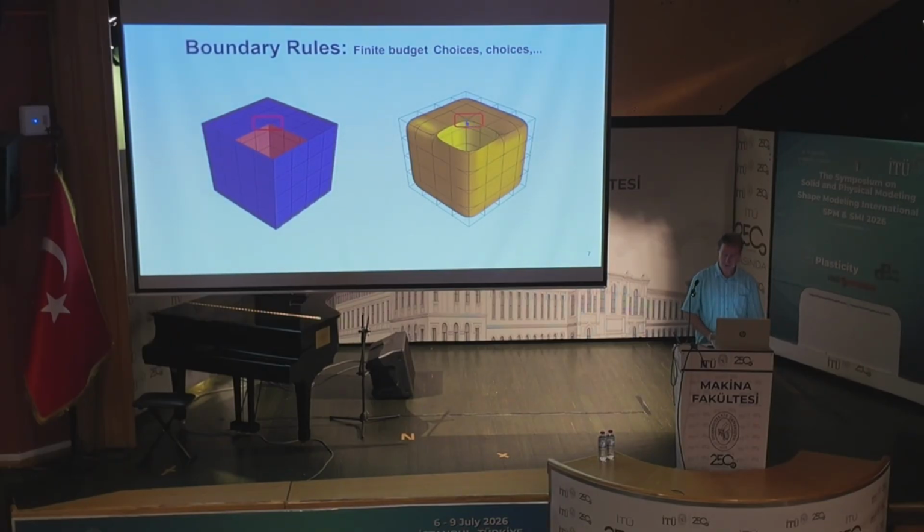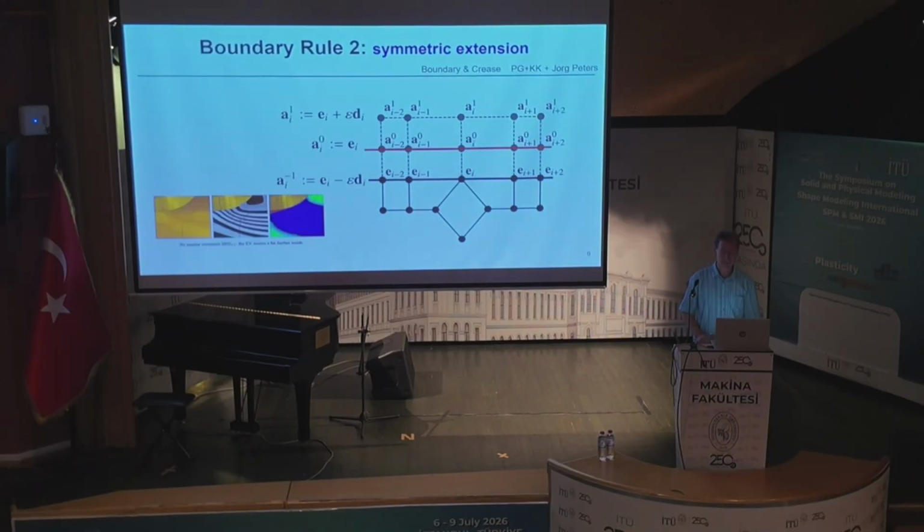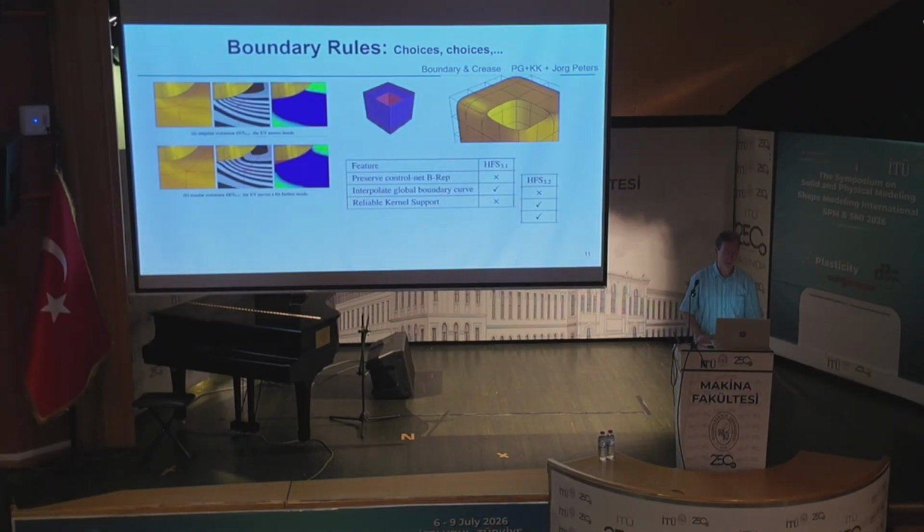Actually, it's cheating. It shows you this here, but what's really happening in the vicinity of this point is an infinite sequence of nested rings that converge towards this multi-sided point. But this is what people say is the standard, and you have to replicate it. This has to do with the B-rep. Their B-rep says this is one piece here. In fact, it's an infinite number of polynomial pieces. And now you can look at the paper, and there's rule 1, rule 2, all smart ideas.